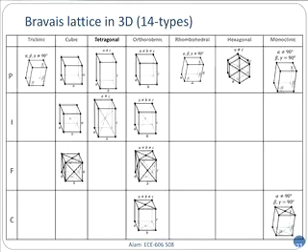But in addition, if you go vertically along the line, let's go on the cubic, the second column, you will see that there are possibilities where the atoms are only in the corner. That's the normal cubic. Then in the second one, marked as I, there's one atom in the middle of the body. That's body-centered cubic. Makes sense, right? One atom in the body. And the third one is face-centered cubic, because there are 6 faces and you have one atom in all the 6 faces. So that's the face-centered cubic.